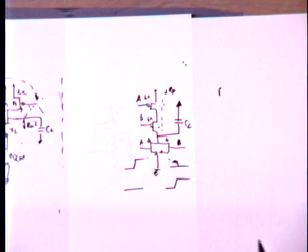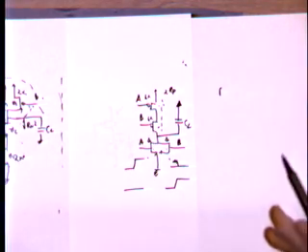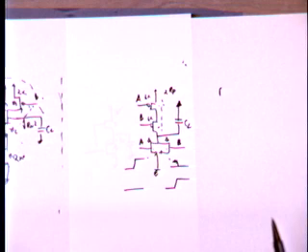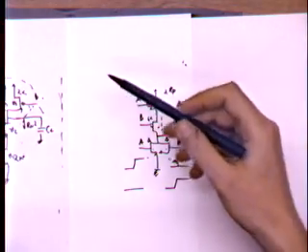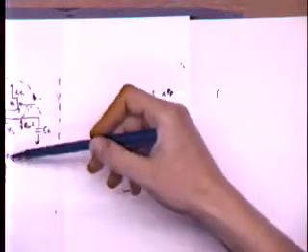The same is true also for NOR gates. So if I give you NORs only and inverters, or NANDs only and inverters, you can always implement any arbitrary logic function. But the interesting thing is, which one would you choose in practice?